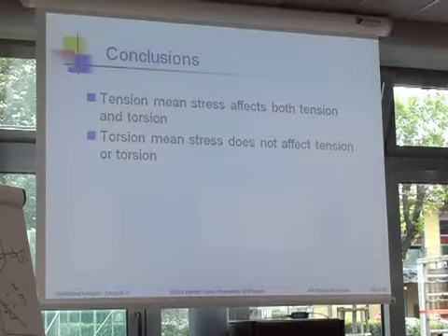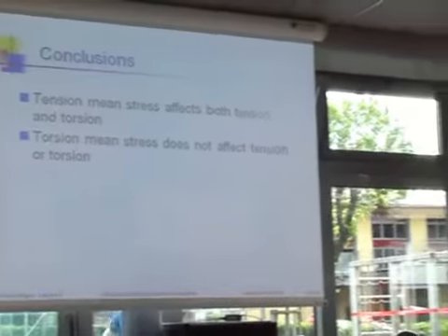So first of all, you say, okay, I need to do something about the shear stresses, because I know shear stresses are responsible for fatigue. Would you like to use the maximum shear stress or the octahedral shear stress? Either one, they're not so different. So I want to say, okay, I know I need the cyclic shear stress. And what about the mean stress?